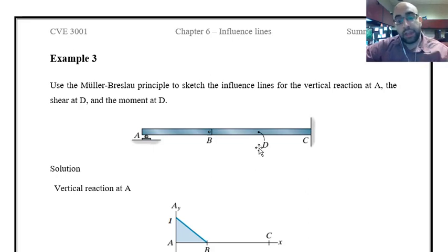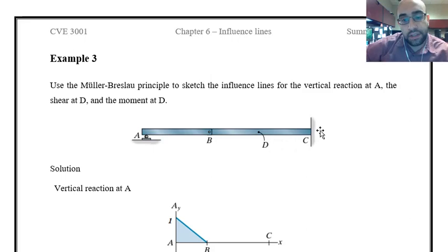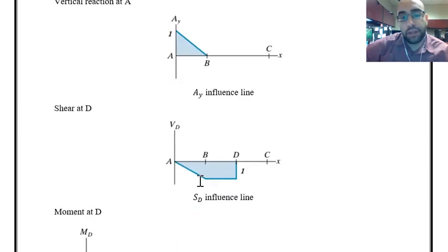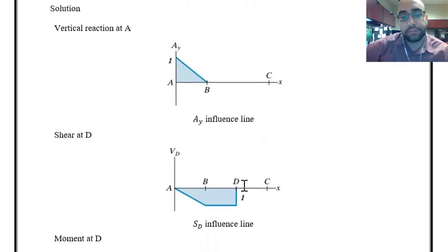which means I have to apply the whole unit displacement on the left segment. It will be moved up. The right segment, or the right section of D, will be horizontal as it is because of this fixed end. We will have a unit displacement on this, and then we will have a rotation at D because of the hinge. That's what we have over here. Unit displacement. Left side of point D is parallel to right side of point D.